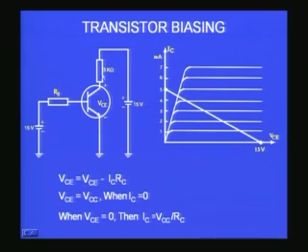Now, you can see on the left side there is a circuit which is again in common emitter configuration, and you have connected your RB, the base resistance, along with a base voltage source VBB. Similarly, there is one collector resistance, which is here 3 kilo ohm, and that is connected to another collector emitter voltage, which is 15 volts, the VCC supply as it is called. Now, can I use this circuit to bias the transistor?